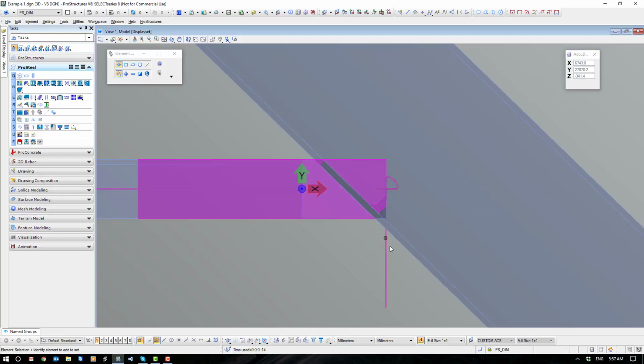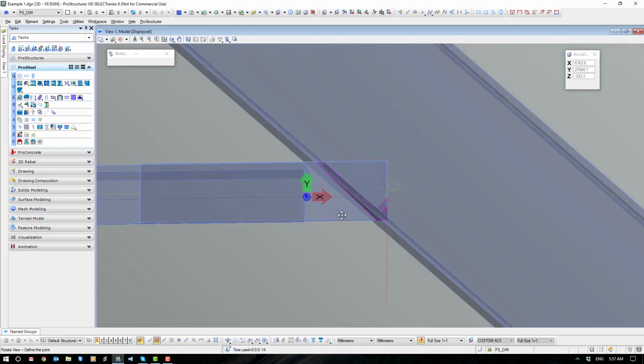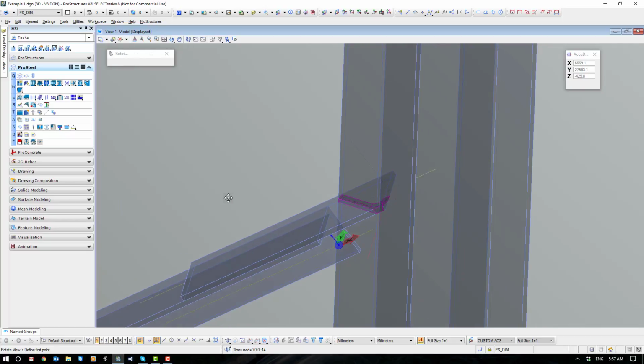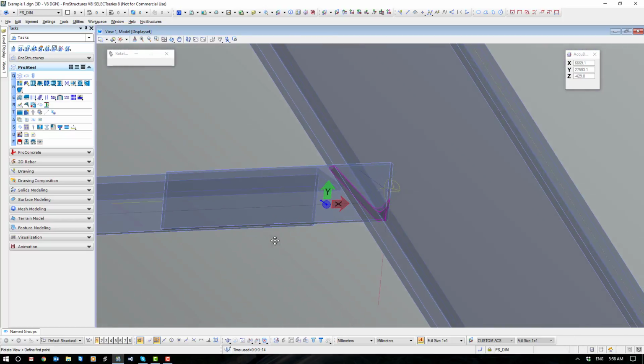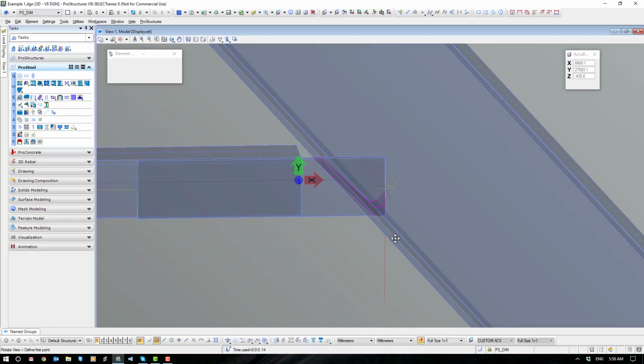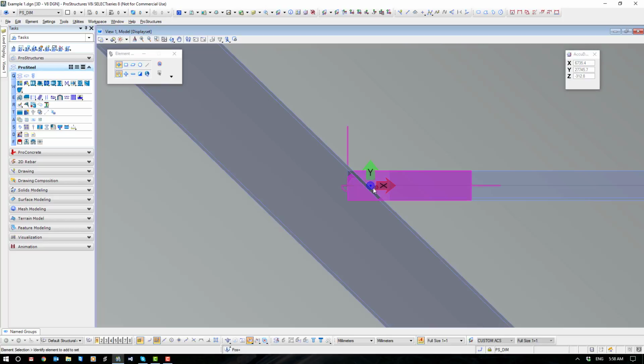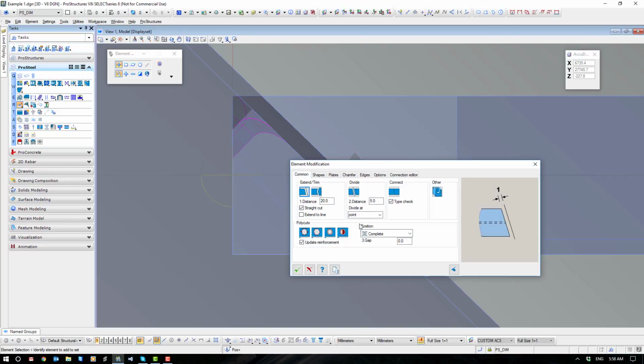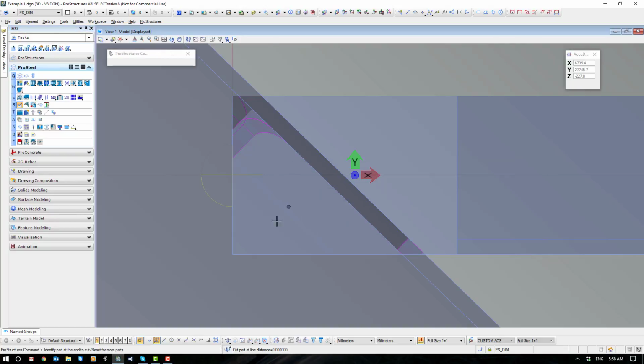Now this time we don't want to cut this off square. This time we do want this cleat here to match the profile of the bottom of the beam. So if it was a compound cleat, it would be very important to look square onto this face of the cleat, and the first line at the underside of the beam is where it interferes. So I don't want to cut it off at a distance. I don't want to cut it straight.